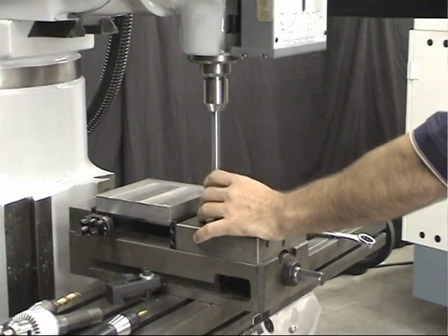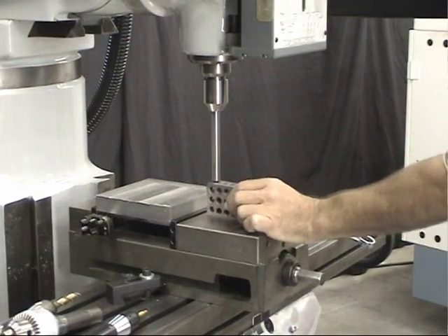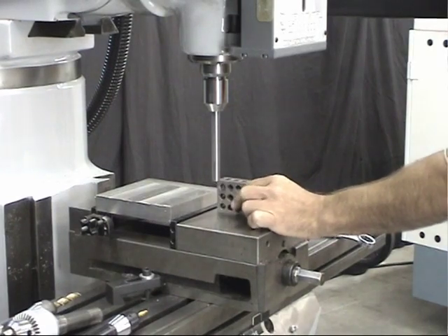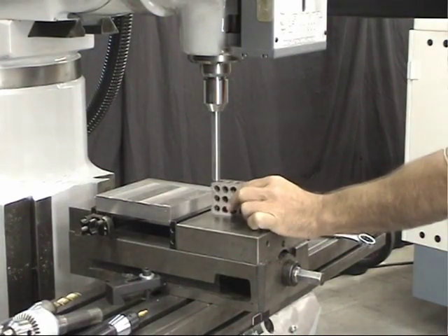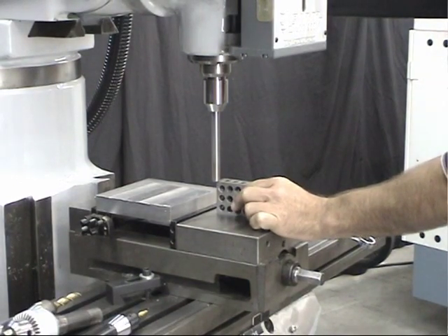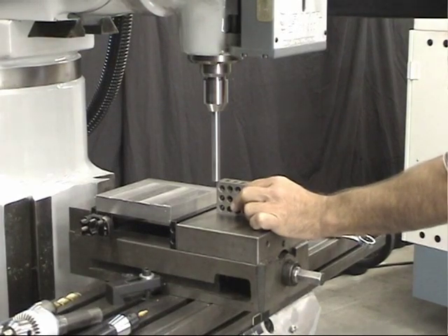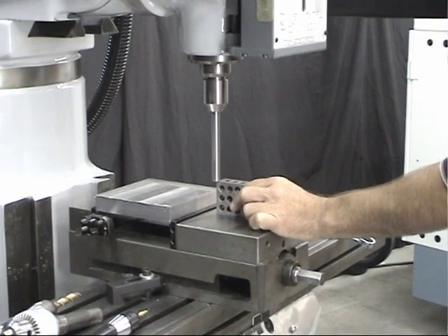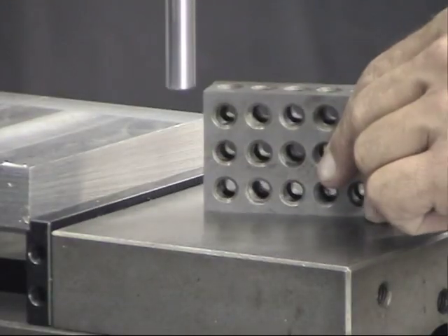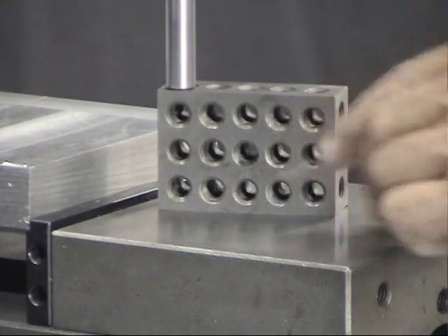Each time moving the 1, 2, 3 block out of the way. Now the goal here is for me to just touch off the reference tool until it just grabs the 1, 2, 3 block. I just got to that point. Now I'm backing up a little bit because I was jogging down 10 thousandths at a time, and I switched over to 1 10,000ths and I'm backing up so that it just kisses the 1, 2, 3 block.